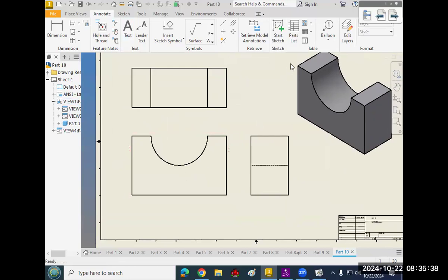Okay, we have curved surfaces. First thing is center mark. Click on the curved surface. That's our only curved surface. And so that's going to be where we dimension things to. We just need to dimension the size of curved surfaces, which this is the only curved surface. So we can go like this or like this. Either one is fine. And we'll make it bigger.